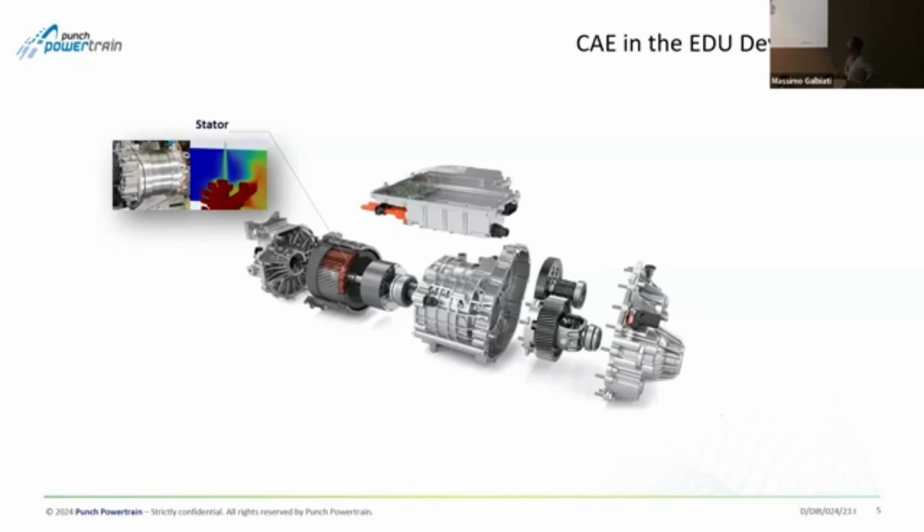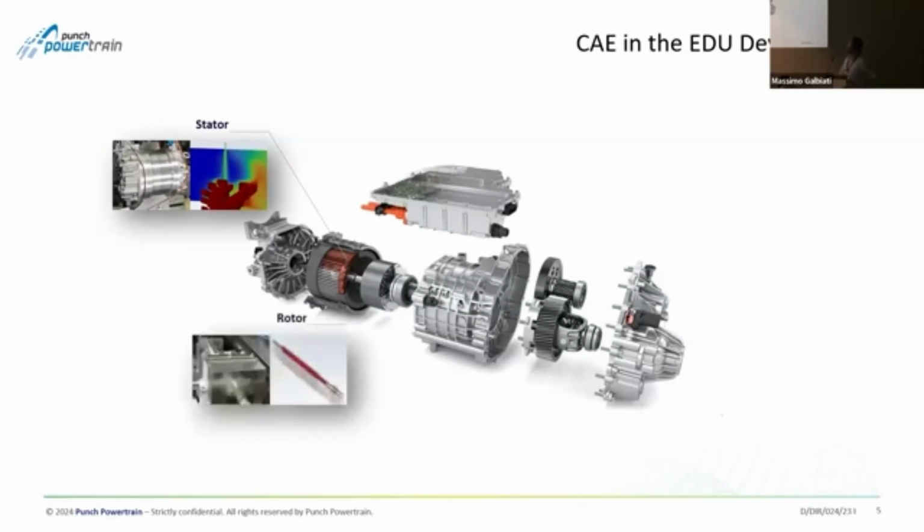For example, for the stator, the cooling of the end windings, which was presented yesterday, I guess. We need also the simulation, and I performed simulation for the rotor cooling. It's a quite interesting system that takes oil from the gearbox to cool the magnets at some working points, and not, of course, for all the applications or for all the clients.